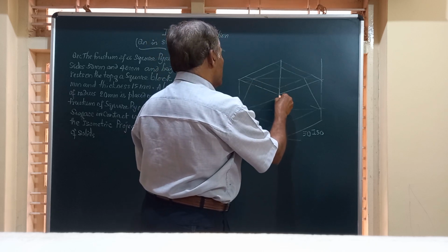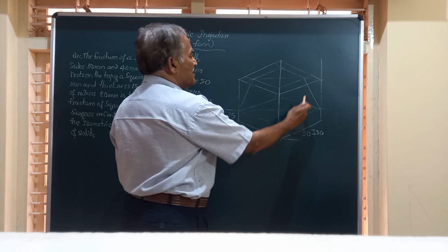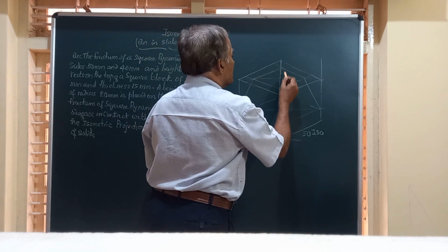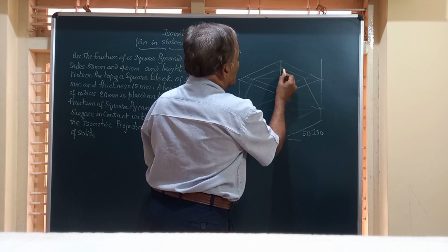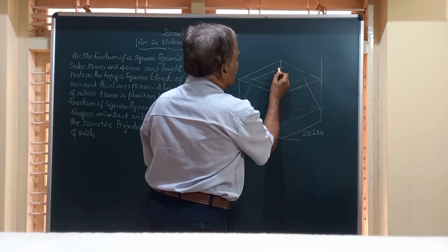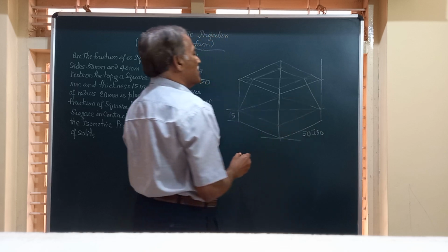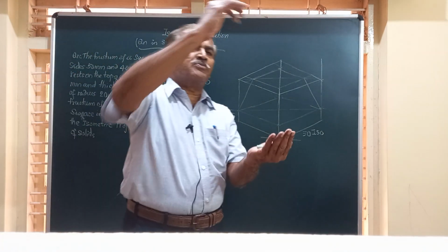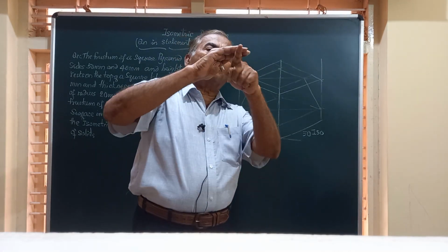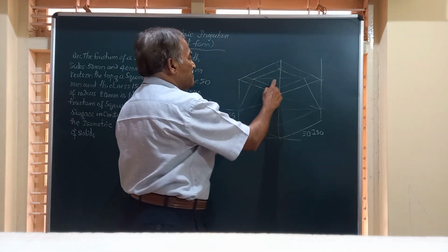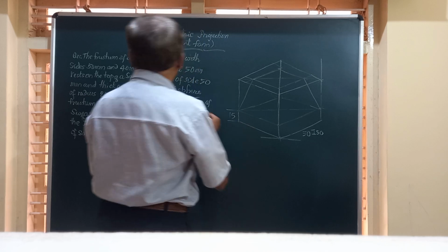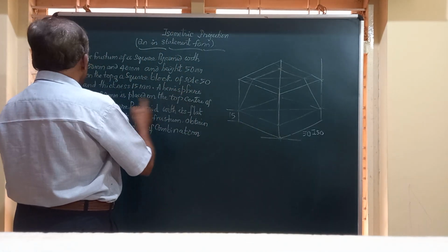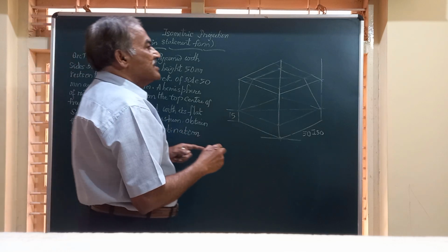Top one, yeah, from here we are going to draw three thin lines. So this is the frustum of the square pyramid, which is just above the top surface of the rectangular block. Friends, over this we have a hemisphere which is placed with the flat surface in contact with this. So friends, that has a dimension of how much? A hemisphere of radius 20.